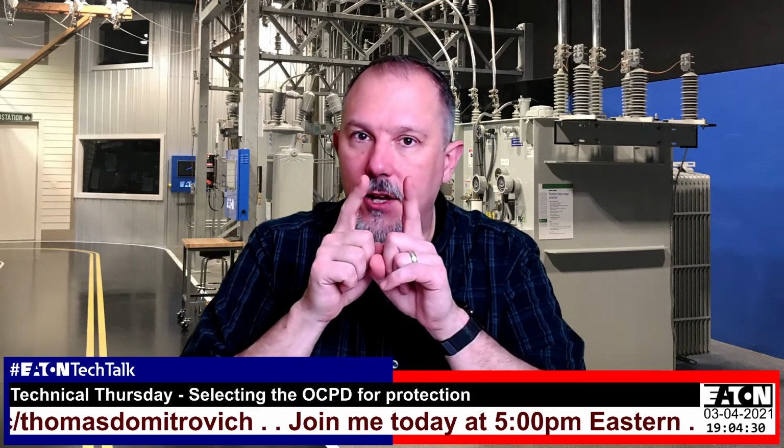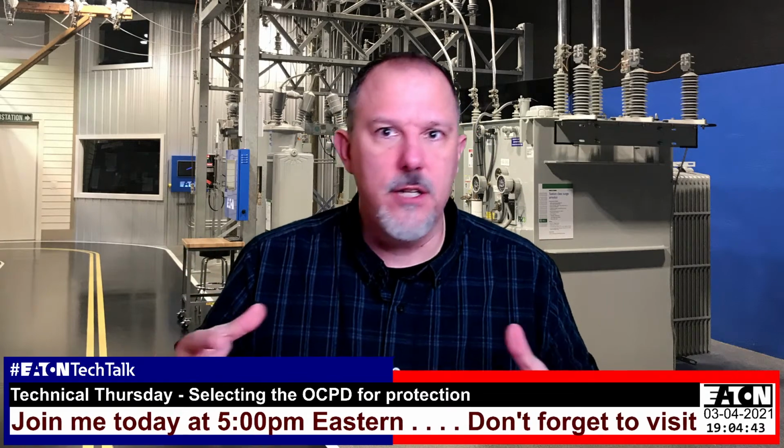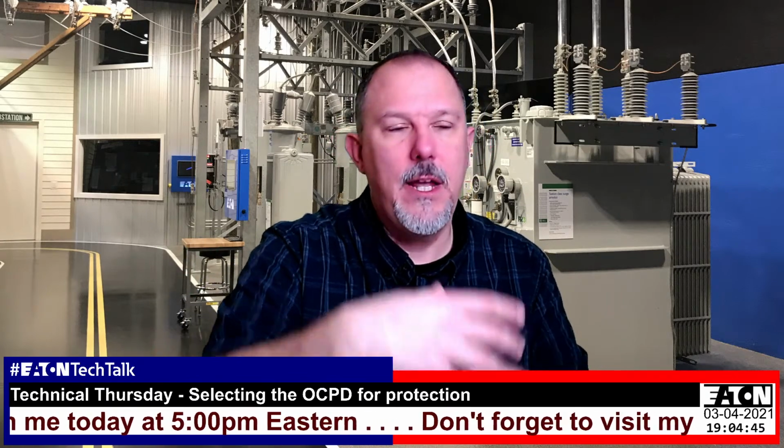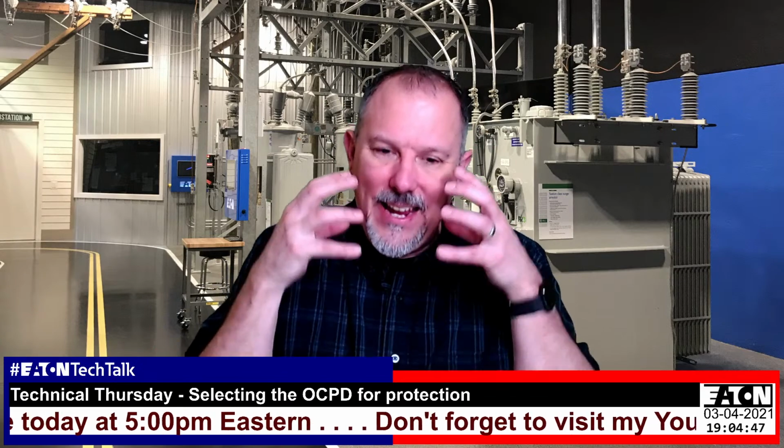But I also need to think about my electrical worker, and the arc reduction maintenance switch is the only technology that's going to look downstream. ZSI, unless you nest downstream, doesn't help downstream. Arc quenching technologies don't look downstream. They look in the box. So in 240.87, the technology that looks downstream is your arc reduction maintenance switch.